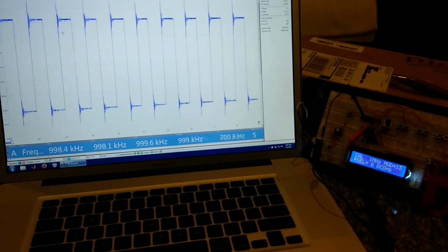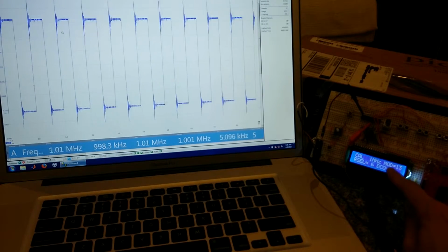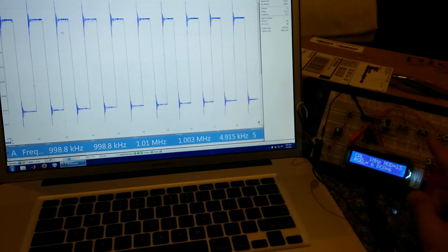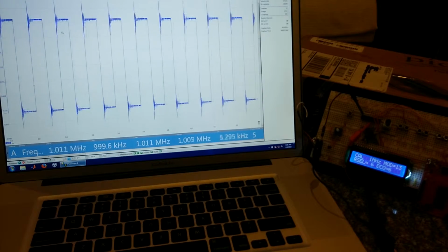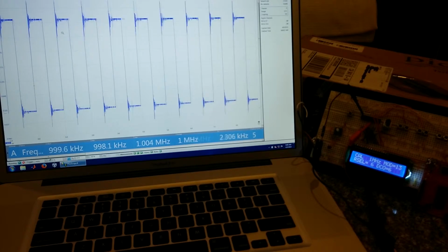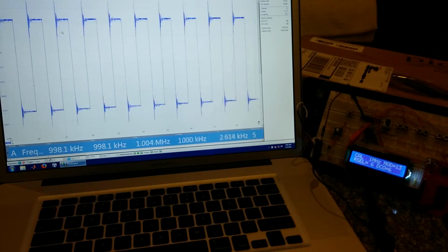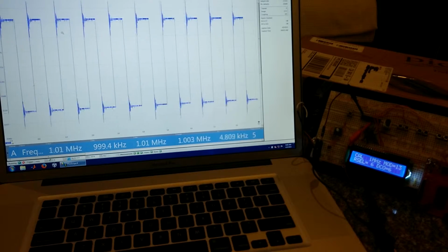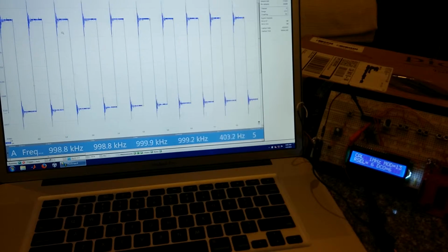And let's talk about some things that you might have noticed. The first thing is this new bit field called the modulation bit field. Now you ask yourself, well, what is that? And how come I didn't talk about it in the normal DCO control? Is it just a calibration value, or can I use it in DCO control? And the answer is, you can use it in regular DCO control. The reason I didn't talk about it is because it just multiplies the complexity, and I got a little bit lazy, sorry to say, and I didn't take down all the values to be able to do the application, but I'm going to go ahead and talk about it now.